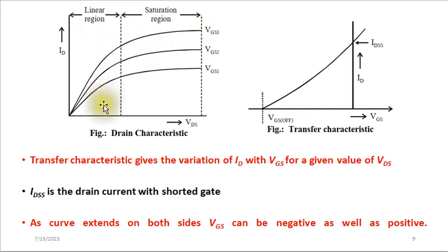Okay? And anything below these curves is what we call the cutoff region, where the voltage is not enough to turn on the MOSFETs. And whenever we want to use a MOSFET for switching, because that's the application of the MOSFET in power electronics, you find that we operate it in the linear region, where there is a direct proportion between the ID and the VDS.